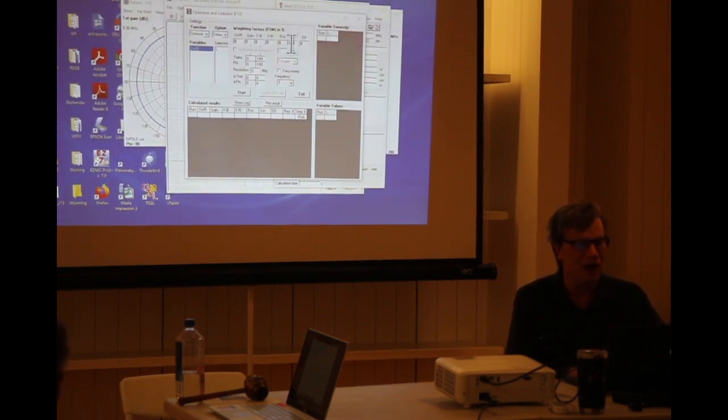This 100 does not give you a number. What it means is 100% priority. This is our only priority. We can put different priorities on different numbers, but in this case, it's just a dipole in free space. We want to make this thing resonate, so we want to change the length of L. This is the parameter that we can change, and up here is the priority.